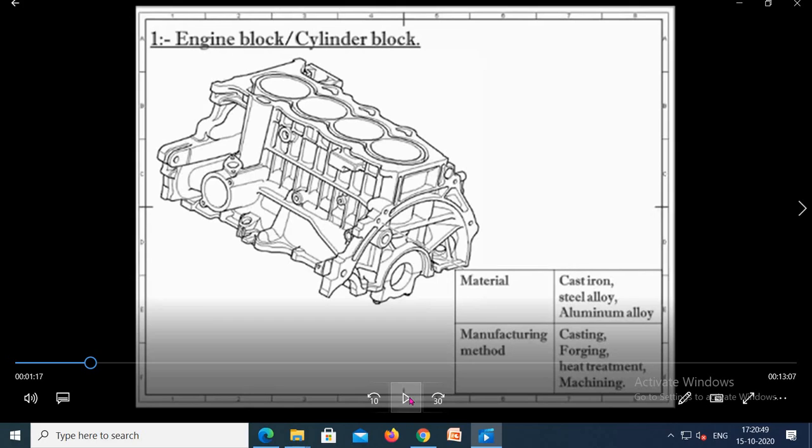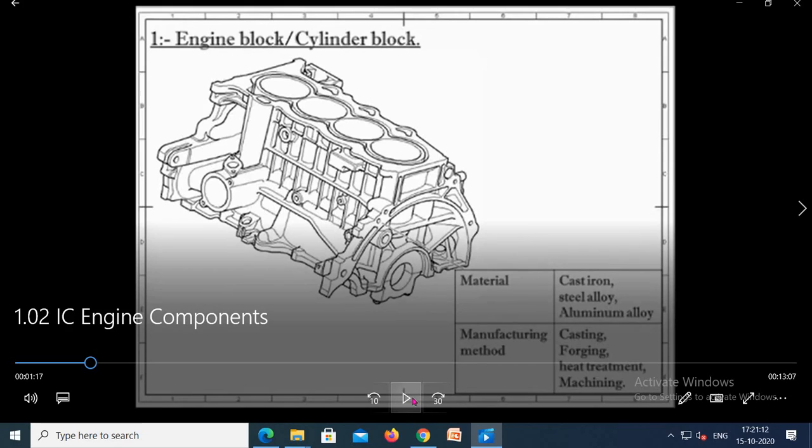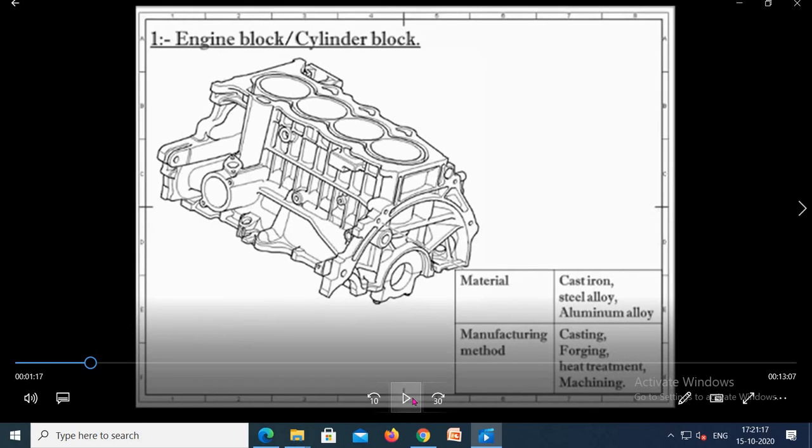The engine cylinder is the most important part of the engine, in which the air fuel mixture is burnt and useful power is produced. As the cylinder block contains the cylinder, the combustion chamber is inside the cylinder. So it gets a lot of heat during the burning of the fuel at the end of the compression stroke, and that's why it is necessary to cool down this entire block with the cylinder piston system. So it is necessary to have a certain cooling system, either a water cooling system or an air cooling system, according to the type of the engine.